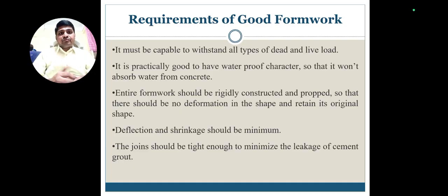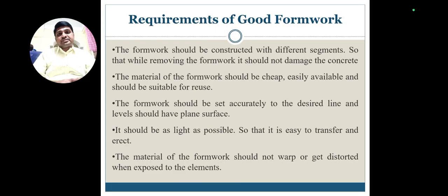The entire formwork should be rigidly and properly constructed so that there is no deformation in shape and it retains its original shape. Deflection and shrinkage should also be minimum. The joints should be tight enough to minimize leakage from the concrete.